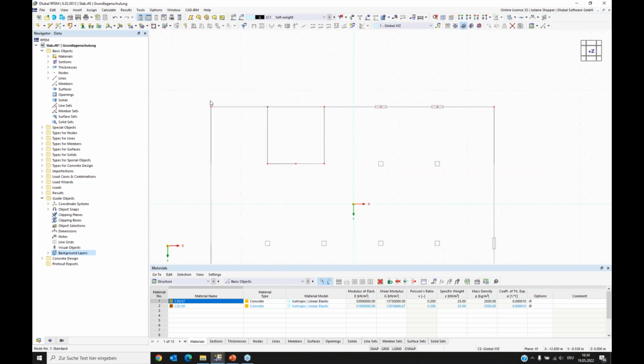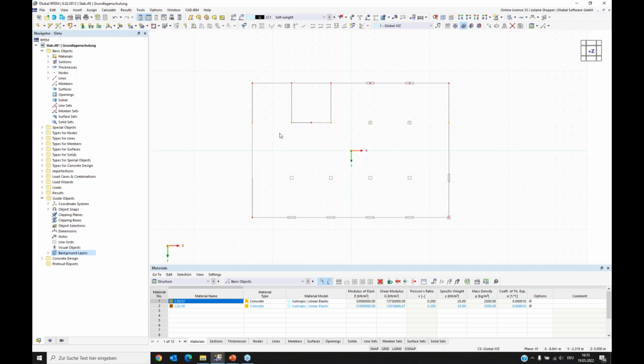So I have to select them. I want to copy them. With pressing Control, I can again and again add the selection. Okay, now I want to use drag and drop. I again press Control and I can take the node and copies are created and I can put them at the place where I want them. Here's the end of the wall and it fits. And now I can see the newly created nodes again are selected, so I can go on with them.